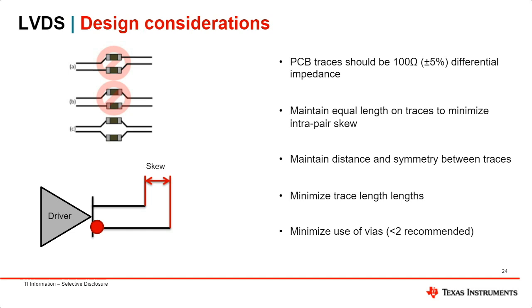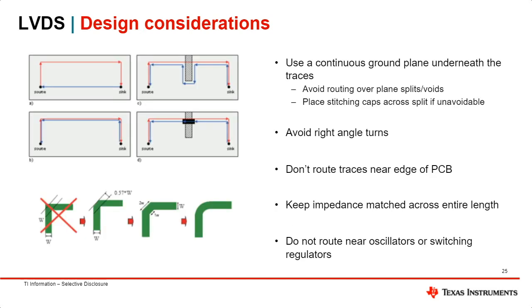In addition to that, it's recommended to use a continuous ground plane under the differential traces. Of course, avoid routing with right angles. Don't route near the edge of PCBs or near noise sources such as oscillators or switching regulators as well.